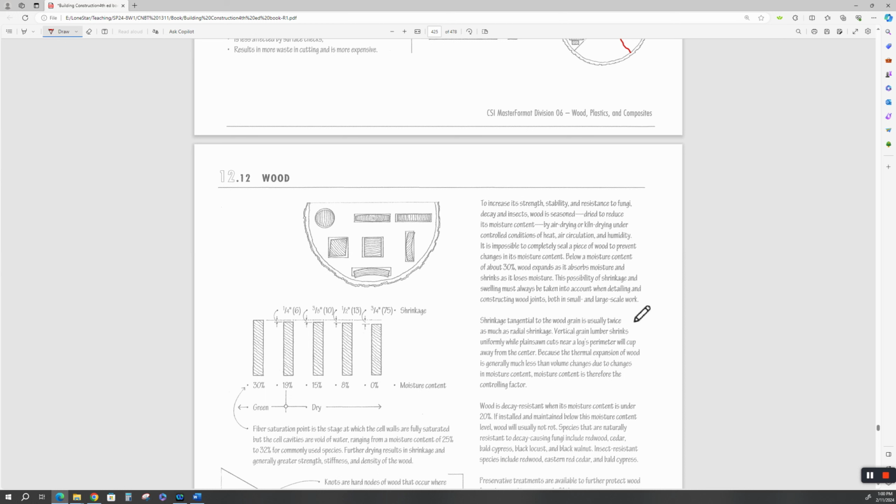Now, when you're doing wood framing, nobody really cares about this. They don't take this into consideration. The wood is all kiln dried and it's stamped and it's bundled and put on a truck and sent out to your job site. Nobody waits several days for it to acclimate. They just bust the bands and start grabbing the lumber and cutting it and framing. Because as it's going up, it will settle, and you're just going to have some slight dimensional changes, not to this extent.